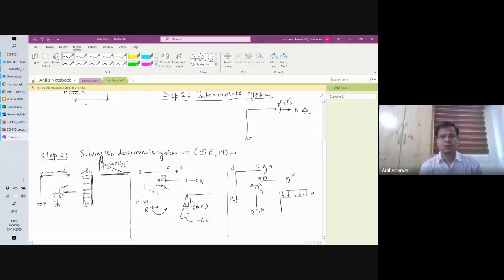Okay. Since I was calling the upward drawn moments as negative, downward drawn moments I'll call positive. Similarly, since I was calling the leftward bending moments as negative, this one will be rightward because you have tension on this side, right? So I'll call these positive.